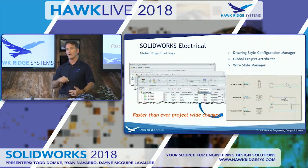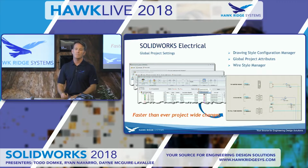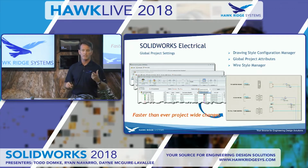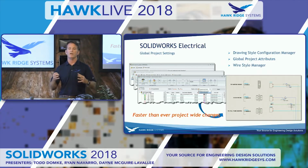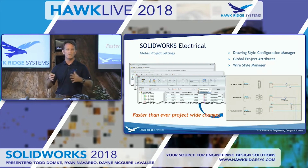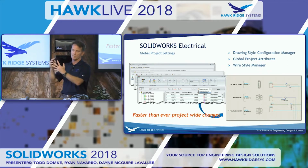And now on to the SolidWorks Electrical tool, which is a few years older. Just another big one. This is our tool that allows us to design full electrical systems with a 2D schematic tool, and then that schematic file drives the placement of wires, cables, and harnesses in our 3D assembly. What we can do this year, as these projects get very complex, with multiple sheets, reports, and tables, is this: it could get a little difficult if you want to change something like an attribute, maybe a wire color. You may have to change it in more than one place, and that just opens you up to making mistakes. Now you can control those at a very high level, at the global level, make one change, and it trickles down throughout those complex projects. Again, just requiring less work of you and helping you avoid mistakes.